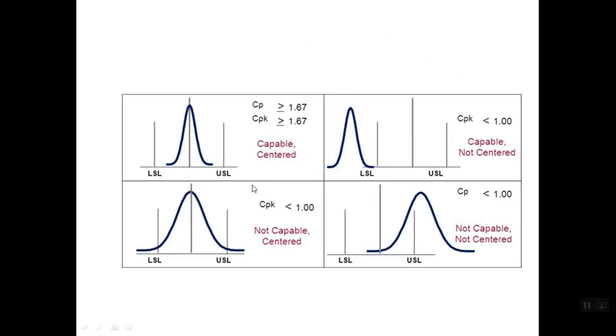So it looks like this. You see your distribution. Distribution means that at 1 million tries, the results are within this bell curve, most of it in here. So the best case is that CPK and CP are at the same value. It means that the CP is 1.67 and the CPK is also 1.67, because the mean and the target are the same, at the center.